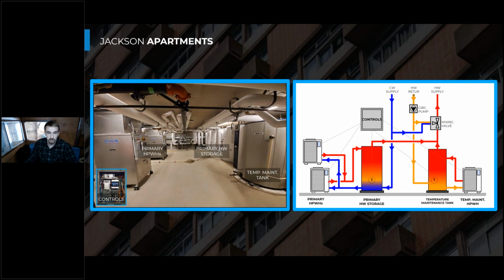And that's a big requirement for some heat pumps altogether, while others are less picky about that entering water temperature. So they're both supplying the mixing valve in parallel, and anytime someone needs hot water, that extra hot water is coming out of the storage and being supplied whenever they need it.